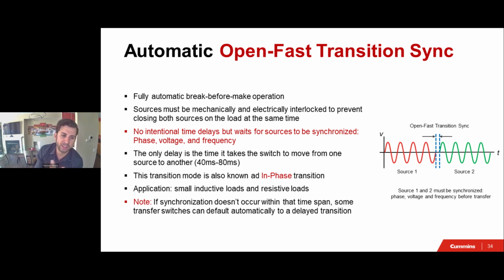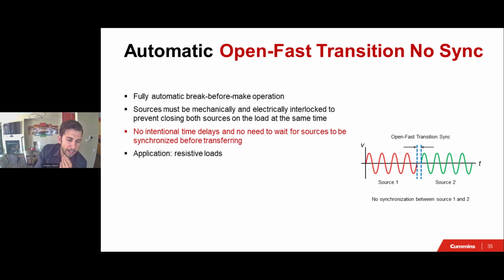And then, for the open transition sync, typically you want to go with the typical application. Again, small inductive loads, resistive loads for sure. Small inductive loads, anything less than say 20 to 15 horsepower. Or you're going to refer to the NEMA MG1 to give you exactly how long it is, and look at your motor, look at your loads, your inductive loads or capacitive loads, stored energy loads, and then derive